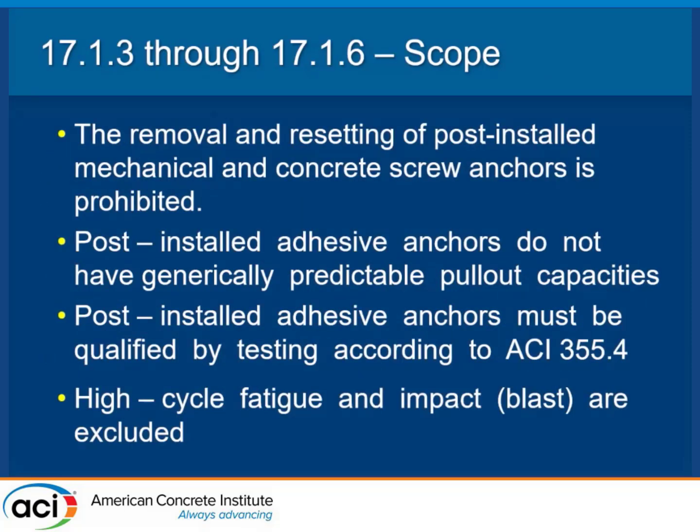All right, so there are limitations in the scope, and that's in the beginning of the section. When you look in Chapter 17, we'll just go through a few of them here, and then we'll have a small break. But one thing they don't want you to do is removal and resetting of post-installed anchors. So they don't put the anchor in and take it out and put it back in again.